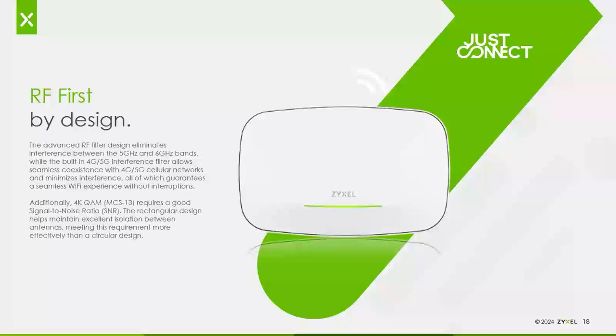And in indoor buildings where you're using a DAS system to rebroadcast your cellular coverage inside the building, those remote units inside the building often use the same cable drops that your access points do, so they end up mounted in very nearby locations in the building where they can cause interference with an access point. So our extra filtering here helps prevent that.